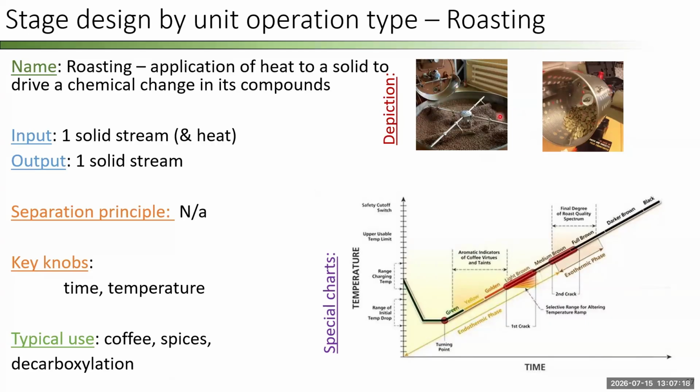Here I'm showing two different types of roasters, a horizontal set where I have a hot plate at the bottom, and then paddles which are going to move those solids around. I could have a rotating drum with those solids in there as they're heated up. The key thing is we often want to keep those particles moving because one edge of that set is very hot and we can end up burning our valuable solids, right?